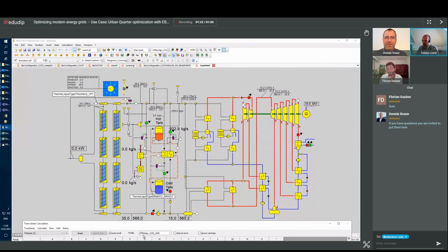And I will stop it right now to show you some of the data that we come in with. Let's go back. So we have 245 degrees at 101 bar. That's pretty hot and pretty high pressure. And at the preheating, we go to 308 bars, and then we are at 311 degrees Celsius. And after the preheater, we go up to 371 degrees with a slight pressure drop from 101 bar to 100 bar.